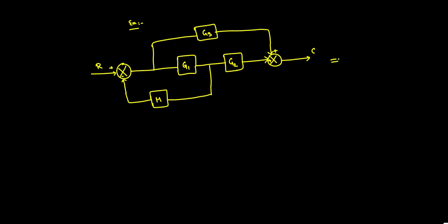How I wanted to bring it down here is R as an input, and it will be a block diagram. So this is the complete transfer function as G, and this should be C. Now the output C is equal to R into G. So C by R is equal to G. That means output by input is your transfer function. I want to bring it into this fashion. Now how can I bring that into that particular fashion?